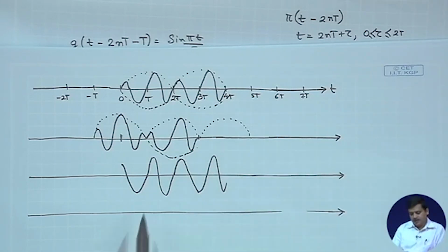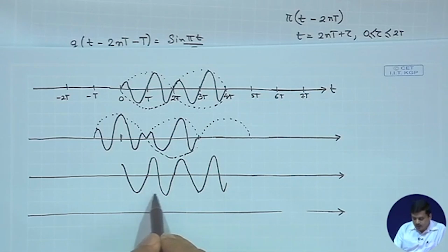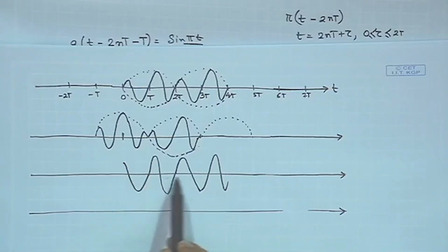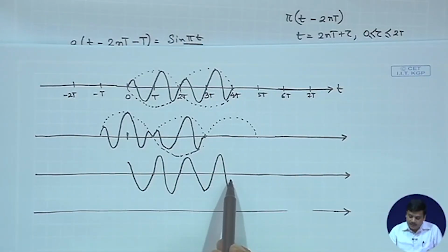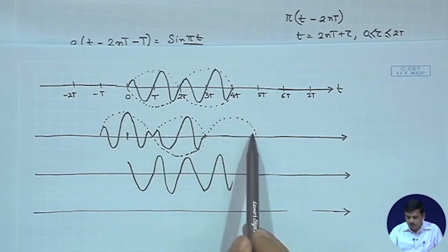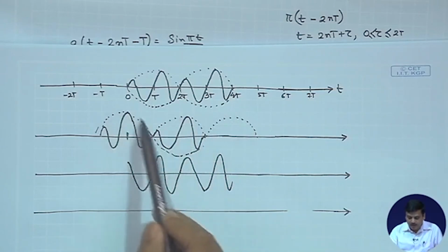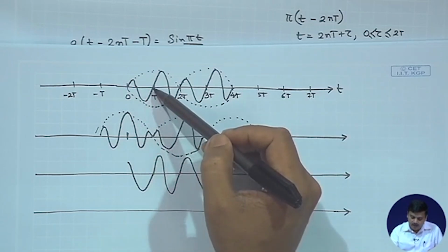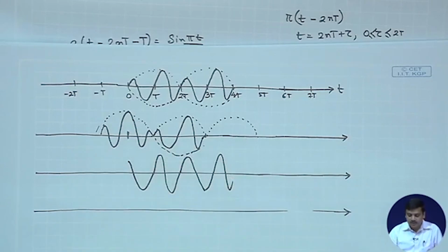So, what you are seeing is that in some portion there is a higher frequency component and in some portion there is a lower frequency component, right. So, as if you are getting two different frequencies. However, since you are doing an FM, there is a continuity of phase, and this is primarily because you are using a pulse shape which is non-rectangular, and each non-rectangular pulse shape is modulating a carrier in the in phase and in the quadrature phase, and they are taking the input bit stream and dividing it into the in phase and quadrature phase.